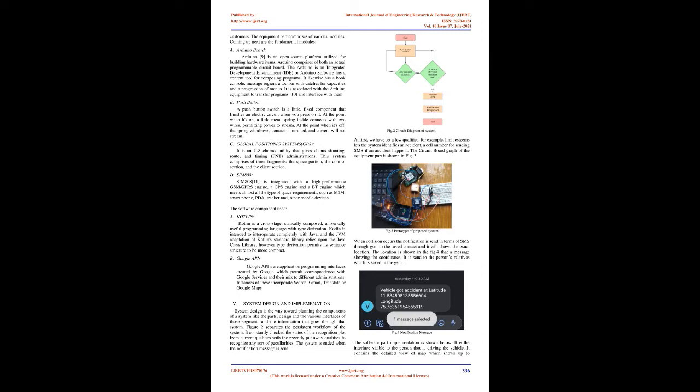1. The Arduino setup is installed in the vehicle's crash guard or in the bumpers of the vehicle on each side. 2. When a collision occurs, it triggers the push button and it sends a notification to the Arduino board. 3. Arduino will take this input and will pass it to the SIM808. 4. The coordinates are shared through GSM. 5. Through GSM the notification is passed to the saved mobile number. 6. It then contains the exact GPS location. 7. The application is used to know the route and location. 8. If the accident is not severe, the person can turn off the buzzer and the device will come back to normal.